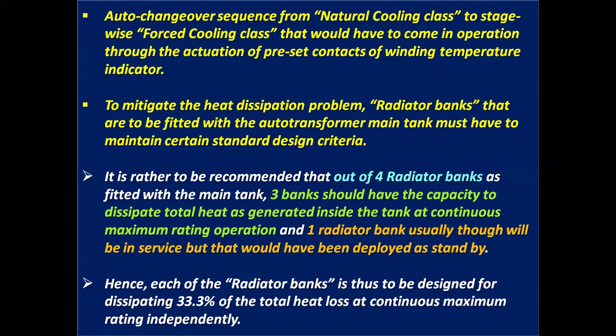Hence, each of the radiator banks is to be designed for dissipating 33.3% of the total heat loss at continuous maximum rating independently.